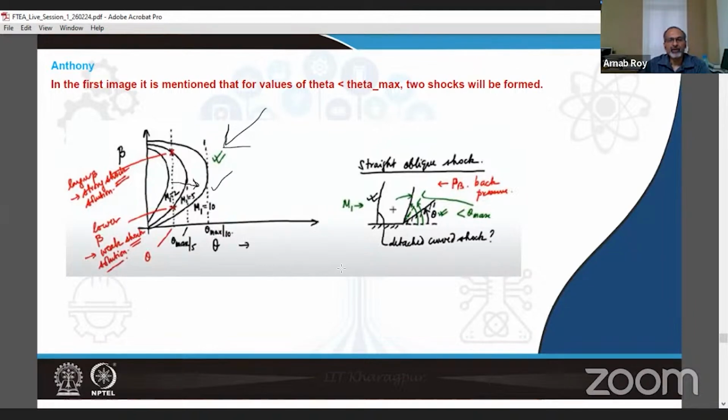The different envelopes indicate that they are going to higher Mach numbers gradually. And for a given Mach number, if we talk about a theta which is going beyond these dashed lines, then we won't have an attached oblique shock. We'll have a situation like this, a detached curved shock. While as long as we keep within the envelope, we get an attached oblique shock.